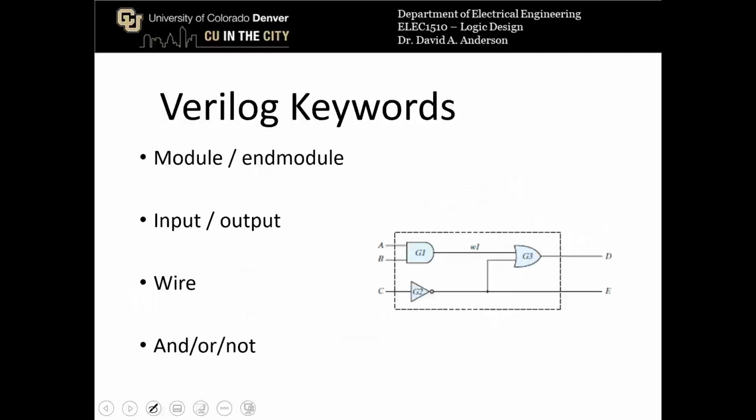All right, so we're going to start out with very basic Verilog modules. Some of the keywords that you'll be using right away represent what you would see in a very typical logic circuit. So it's pretty much a one-to-one relationship between the drawing of the logic circuit and the keywords that you'll see in Verilog.